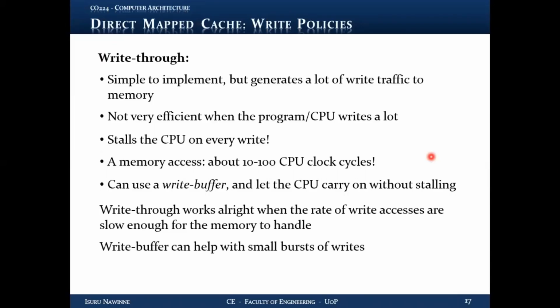You can't let the CPU carry on. You have to wait until some space in the buffer is cleared up before you can let the CPU carry on. So again, you're back to square one. You have to stall the CPU until memory completes one write access. You're only delaying that stall by a number of clock cycles.